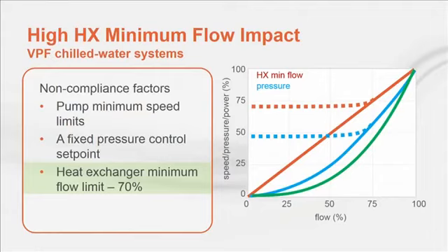Looking at some part load differences, at 50% load, the predicted power is only 12.5%, but the actual power is 34%. At 25% load, the Affinity laws predict 1.5% power, and in reality, it's 34%. Those are significant energy use differences.